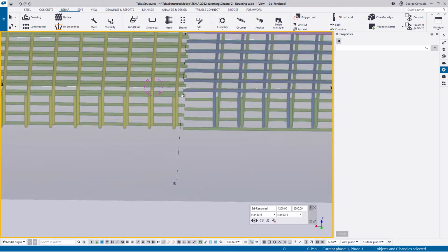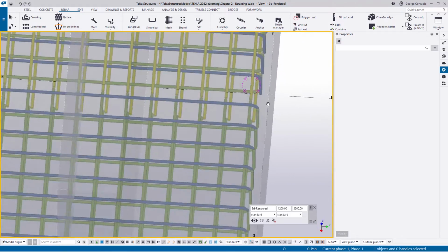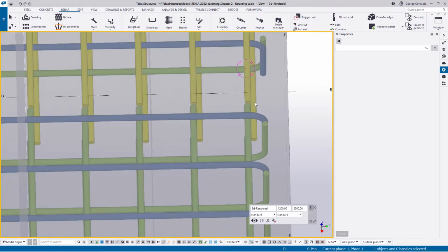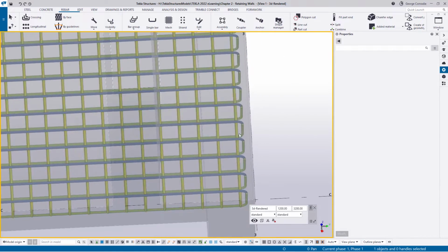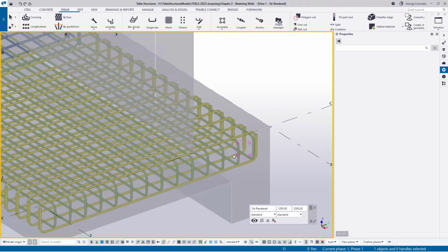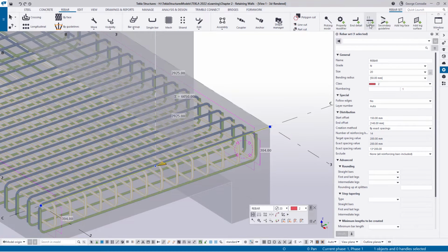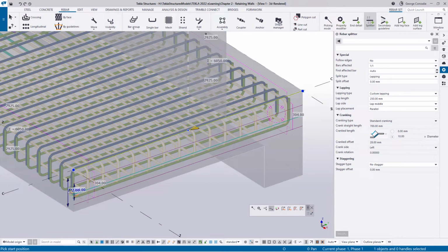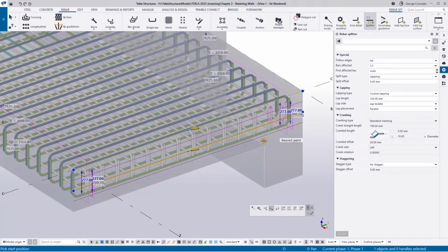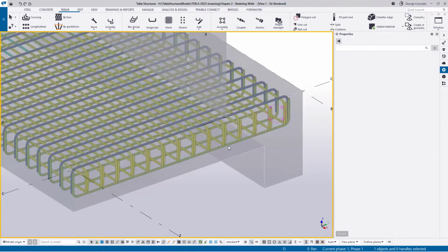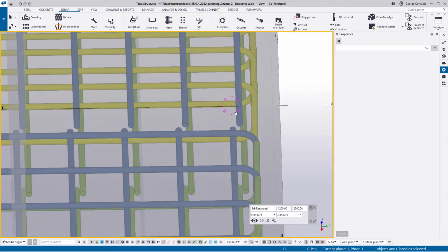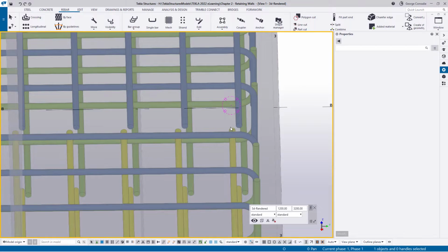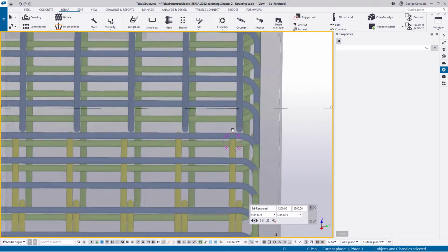Now, if we go back to this end and look at these bars from the top, we can now see they sort of offset each other. So now we can slot these in, and break these on the other end as well. If we come with these and say splitter, and this time we do have a face to pick the center, we click there, and that splits that. If we now return to our interface here, you can see that it just so happens that all we have to do is extend the bars and not move them around, and they won't clash.